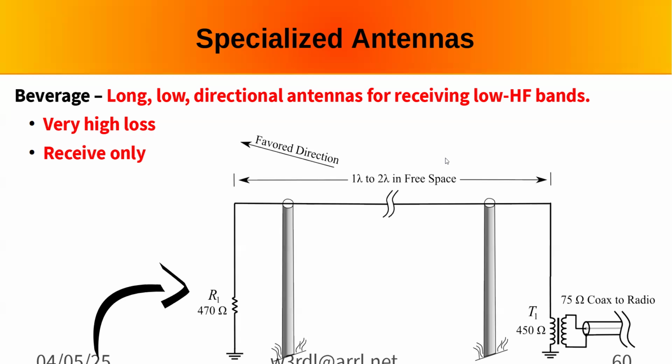Why are they using 75 ohm coax instead of 50? Isn't that going to be a mismatch to your transceiver? Or receiver? Well, yes, but remember, it's only 1.5 to 1. Put a transformer in there to give you 50. It's a good question. That's what I asked. I guess you'd have to ask the guy that drew this drawing.